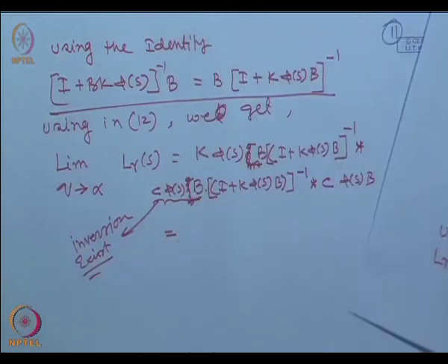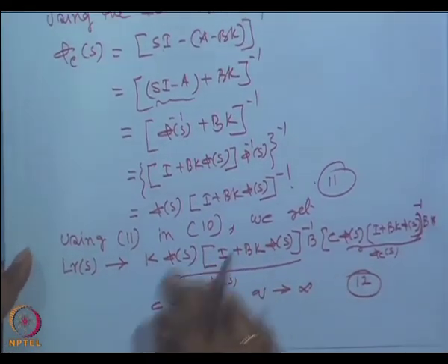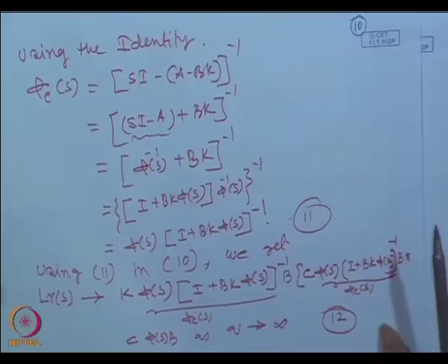Ultimately we will derive this in the next class, some two or three lines are left. We will discuss what our choice of loop gain through the noise process is, and what the loop gain will ultimately come out to be. It will come out the same as the linear quadratic regulator loop gain. So one can recover the loop gain of LQG by properly selecting the process noise covariance. The rest of the portion we will discuss in the next class.